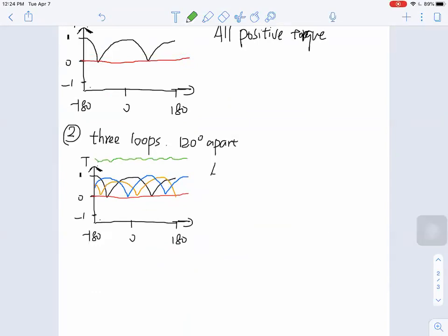If you're adding more wire loops in the motor, think about what consequences you're gonna have. First, if you have more wires, when current passes through the wires, you're gonna have more ohm loss, right? And that's something you couldn't get rid of. Another thing is you're gonna increase the weight of the motor, increase the cost of the material, and also if you have more loops, the inductance of the motor is getting higher and higher.